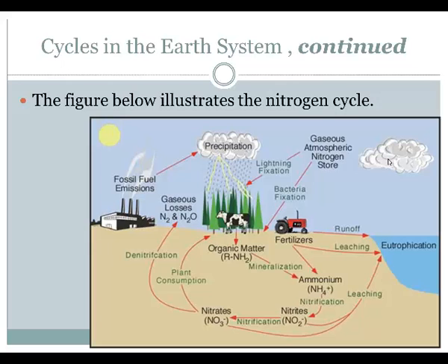This illustration shows kind of the same process, a little bit different of a rendition of it. So ammonia, nitrites. After we produce ammonia, nitrification creates nitrites. Remember, nitrites in much of any form are not going to be very good for our fish at all. But then nitrites can continue through nitrification and create nitrates, which are not nearly as harmful to our fish as the nitrites.